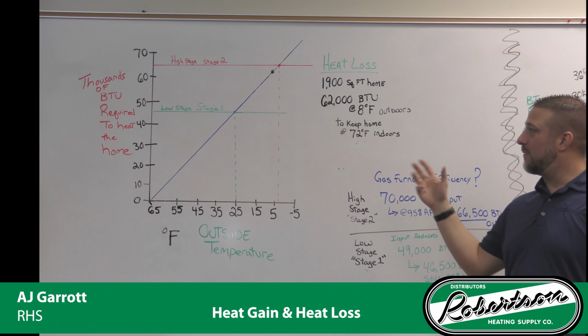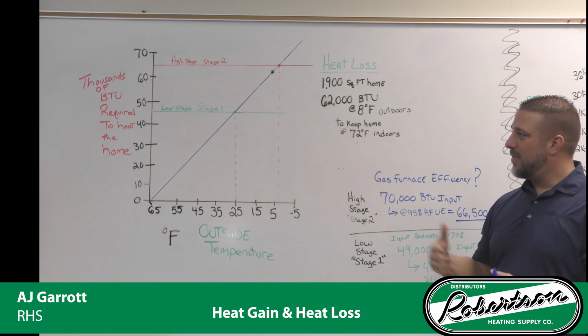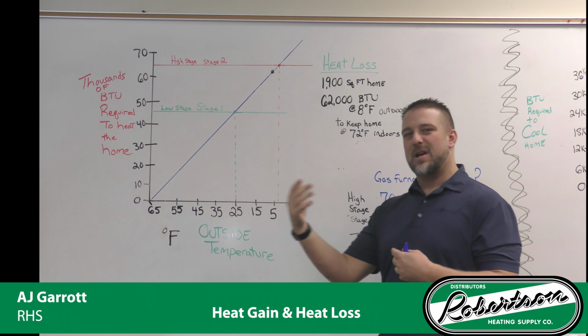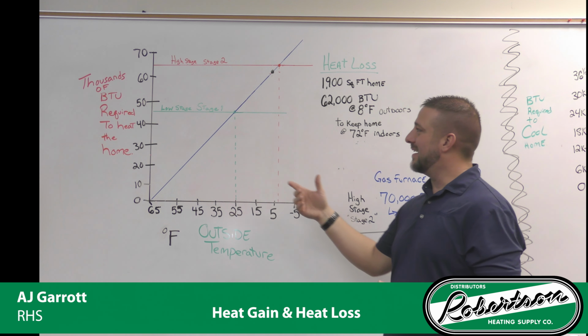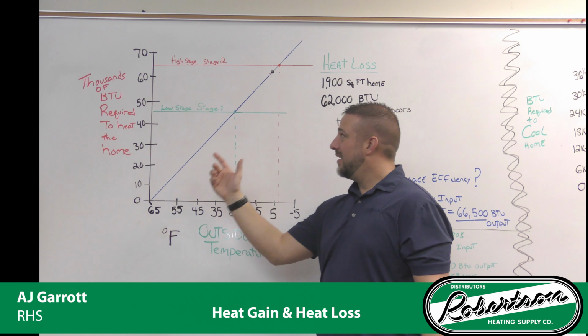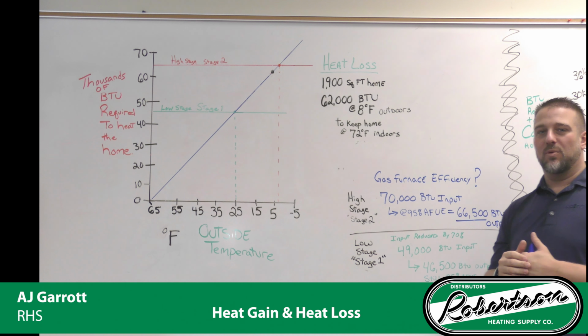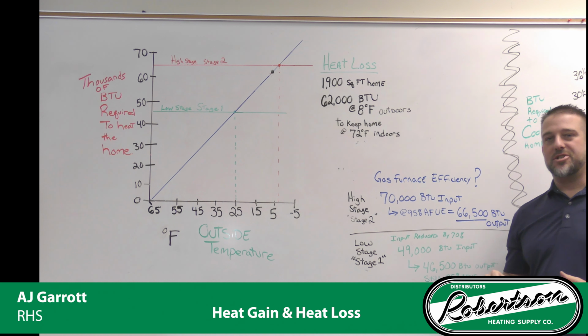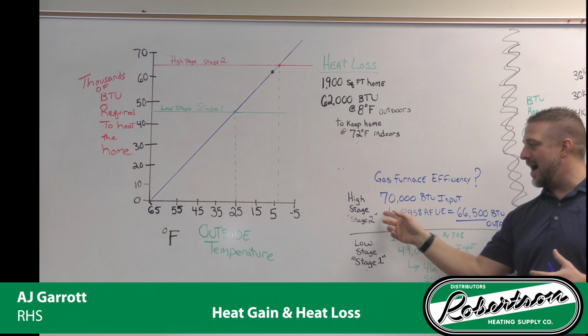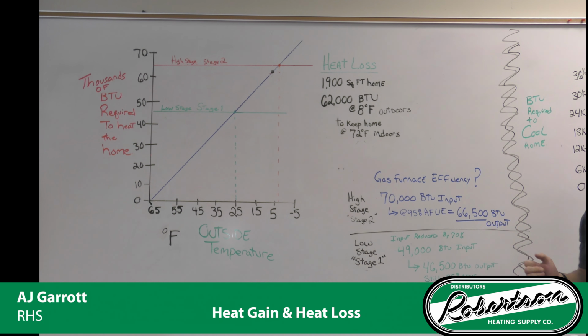Now, for comfort and application, maybe we want to pick a better furnace. So we look at a 2-stage gas furnace. A 2-stage gas furnace, well, how does that work? Well, our stage 2 is going to be our full load or our high stage. That is all 70,000 BTUs going in.